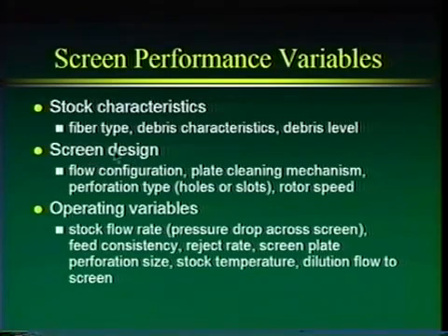And then we've got the screen design parameters. What is the flow configuration? Is it in to out? Is it out to in? Is it both? What's the plate cleaning mechanism? Is it with rotors, or is it with a bump, or is it with steps? How gentle or how intense is that plate cleaning mechanism? Because you can very easily break brittle or soft contaminants, weak contaminants, if that cleaning mechanism isn't very gentle.